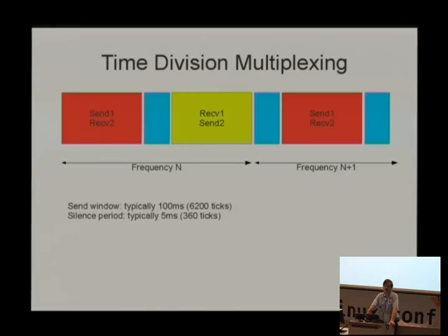When it starts up, it calculates all of these numbers based upon the configuration that the user has given the radios. So the user is able to put in all the parameters for the hopping frequencies and the speeds, the air rates and the serial rates, etc. Now, those of you who are listening to the numbers may have noticed that the link is oversubscribed. Any of you noticed that? So notice that our serial rate is higher than the data transmission rate, and that's quite deliberate. And we actually have some flow control information that's able to cope with the fact that the link is oversubscribed. And it works very well because usually the link is sending a lot more data in one direction than the other.